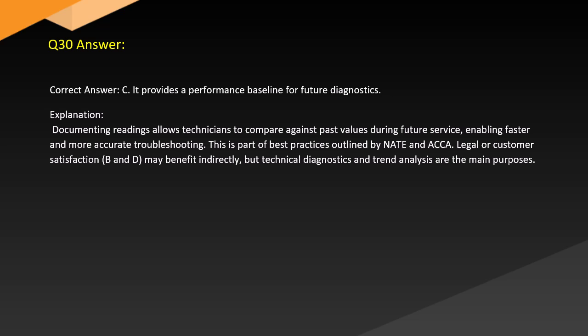Correct answer. C. It provides a performance baseline for future diagnostics. Explanation. Documenting readings allows technicians to compare against past values during future service, enabling faster, more accurate troubleshooting. This is part of best practices outlined by NATE and ACCA. Legal or customer satisfaction, B and D, may benefit indirectly, but technical diagnostics and trend analysis are the main purposes.